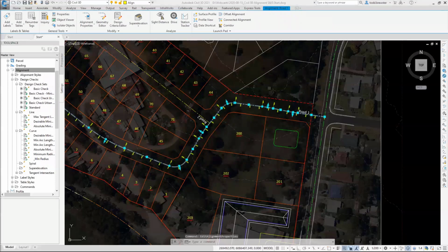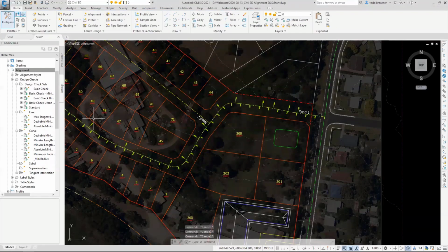So now let's have a look at some labeling. Next tip: station and chainage are interchangeable. Station is an American term for what we would call chainage in Australia. So I'm probably going to be referring to some things as chainage labels, but the software will say station label. They are the same term. Forgive me if I use a term that makes no sense, but I'm hoping most people are used to it these days. It is an American-based product, so in the core of the software, station equals chainage.